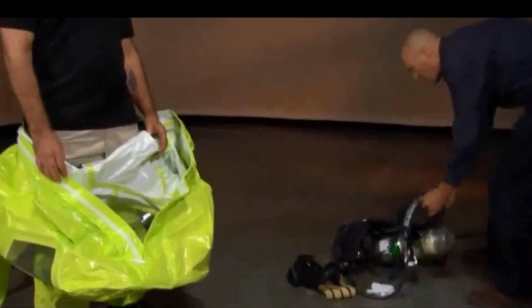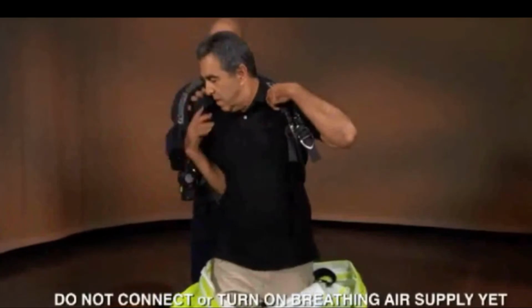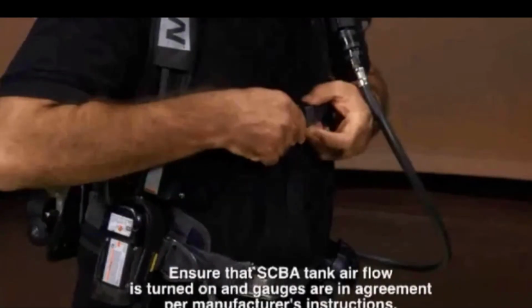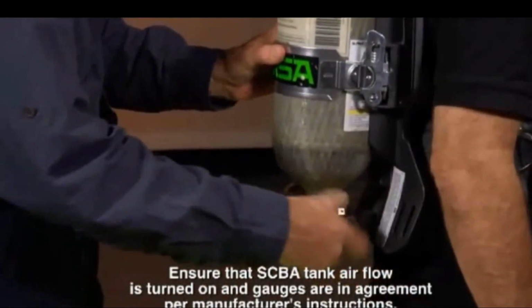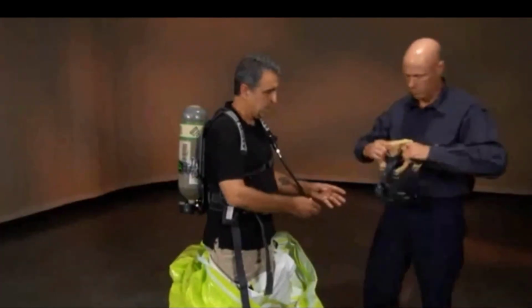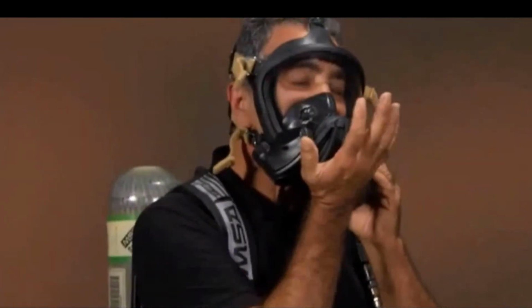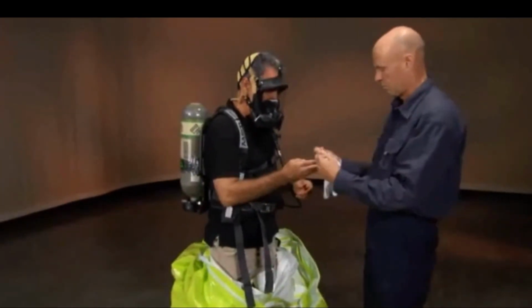Take a few steps. Then sit back down. Pull suit up to your waist and secure interior suit belt if provided. Put on your SCBA pack only. Do not connect or turn on breathing air supply yet. Ensure that SCBA tank airflow is turned on and gauges are in agreement per the manufacturer's instructions. Put on respirator facepiece, ensuring a solid fit. Again, do not connect or turn on breathing supply yet.